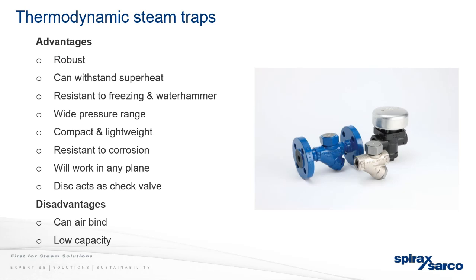Disadvantages: they can air bind. Air can get trapped in there and stop the trap from working. And because of their size and the orifices that they have, they are relatively low capacity. We will cover where they're perfect to use though. Any questions on thermodynamic traps?